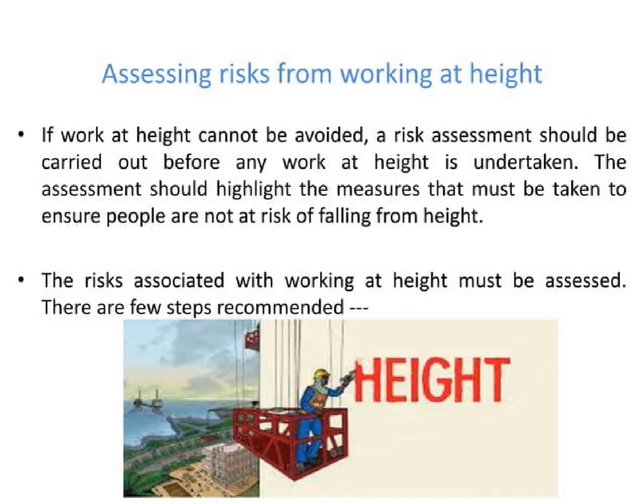This assessment should identify the measures needed to prevent people from falling from a height. Although there are several steps to consider when performing a risk assessment, the most important elements are to identify the potential hazards at height, assess the risks associated with these hazards, and determine the necessary control measures to be taken to prevent any injury.